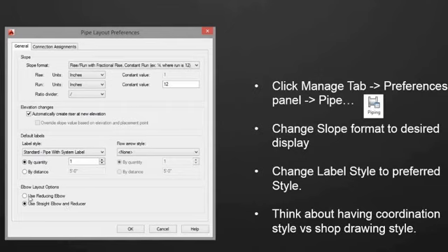And currently our EastCoast software doesn't allow the use of routing a reducing elbow automatically, so we have this set to use the straight elbow and a reducer. If you would like to use a reducing elbow, all you need to do afterwards is just change the size of the pipe on the connector 2 of your elbow, and your elbow will update to the correct size as long as you're using an elbow that supports a reduction in size.